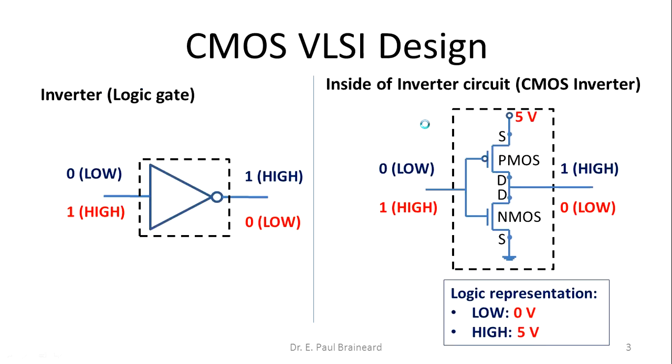Now a question. What is there inside a logic gate? The answer is transistors. In a VLSI based circuit, MOSFET is a predominant device. Again, it is not a discrete N-channel MOSFET or P-channel MOSFET, but complementary NMOS and PMOS, which is called a CMOS circuit. The advantage is less static power dissipation in case of CMOS circuits, details of which we will see in the later classes.